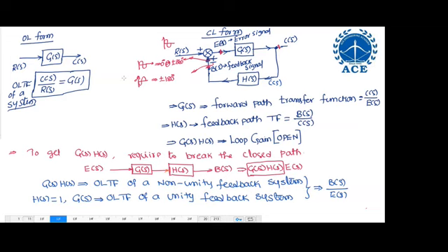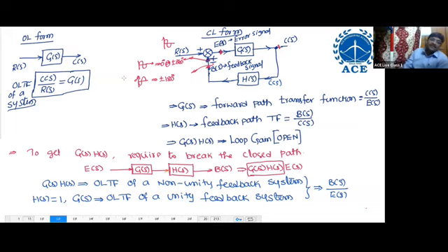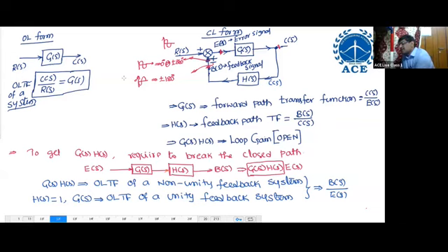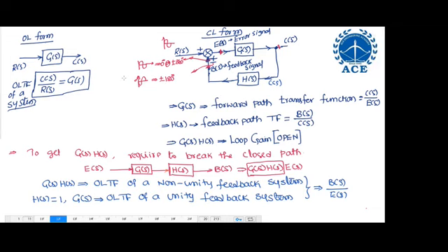Sir, but in networks we took a voltage source of 5 volts and solved it. That source is different. If the capacitor has 5 volts across it, you should not consider that. If you consider it and draw the transfer characteristics, you don't get linearity, because the capacitor won't always have 5 volts; if there is a path, it will discharge. Okay, sir.